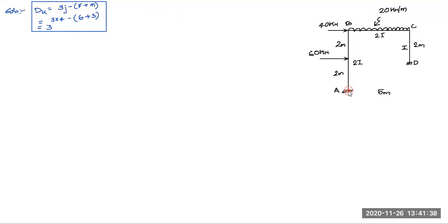So there is no question of any displacement at joint A. Similarly, at joint D, there cannot be any displacements since a fixed support is provided there. At joint B, there can be rotation, that is one displacement. At joint C also there can be rotation, that is another, two independent displacements. In addition, this frame can sway, so joints B and C can get displaced in x direction by an equal amount.